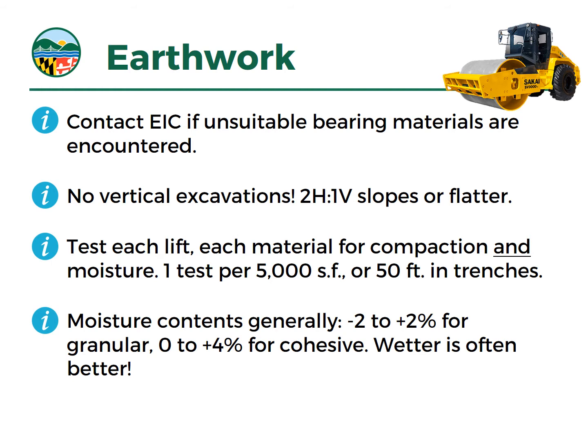Generally, moisture contents range between -2 and +2% from the optimum moisture content for granular materials, and from optimum to 4% above optimum for cohesive materials.